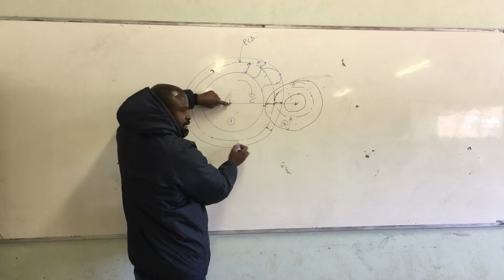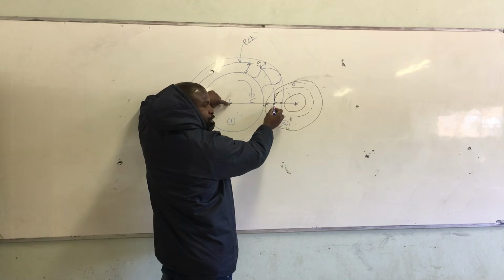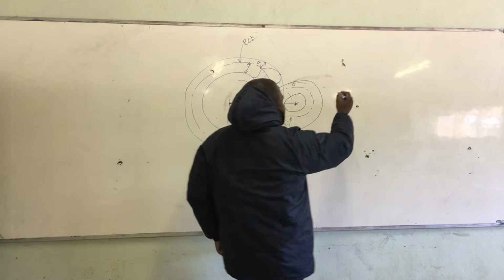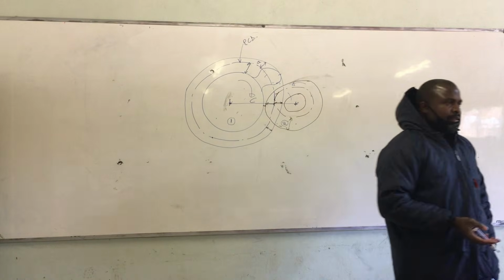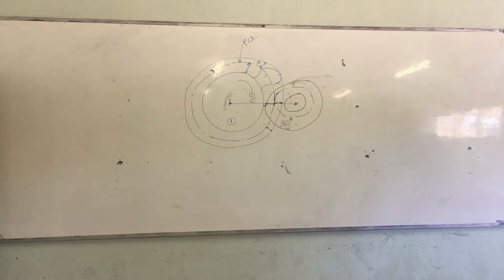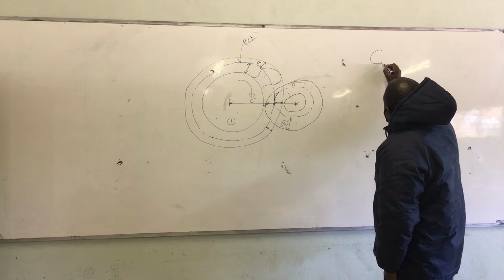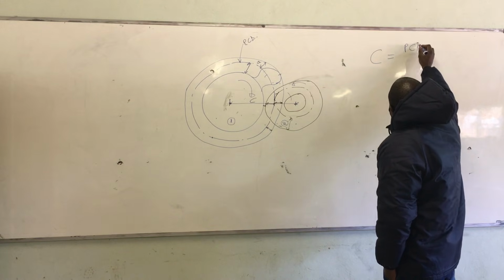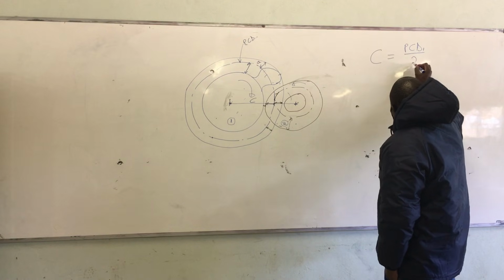I mean, this will say it's a PCD. It's a diameter, right? So from there to there, is it not half of it? It's a radius, right? For you to find the radius, you take a PCD, a diameter, and divide it by 2. So our center distance will be PCD for gear number 1 divided by 2.